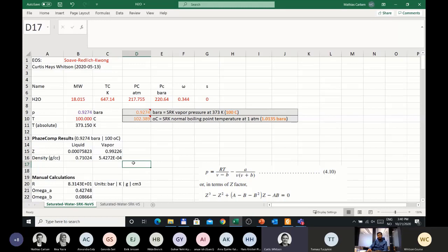Now, even if you do that, the cubic equation of state, if you ask it to calculate the compressibility of water, for example, at 1 atmosphere and 60 Fahrenheit, not at the boiling point, but just tap water coming out of the faucet. That tap water should have a compressibility of, depending on the units, somewhere around 3 times 10 to the minus 6 inverse PSI.